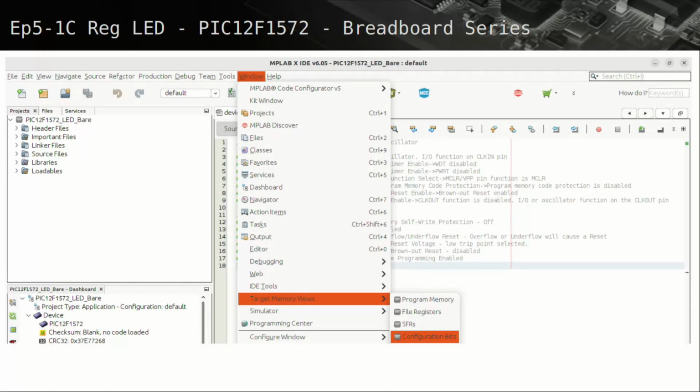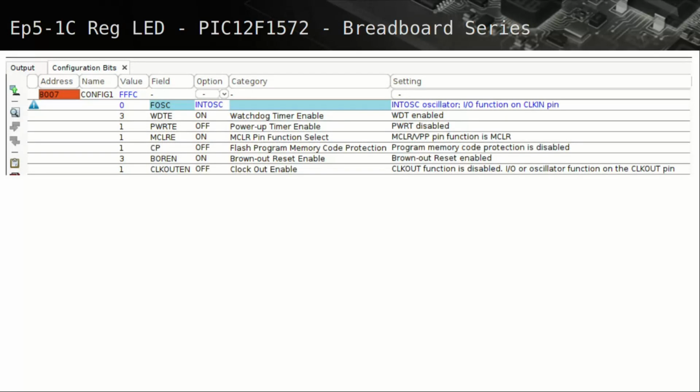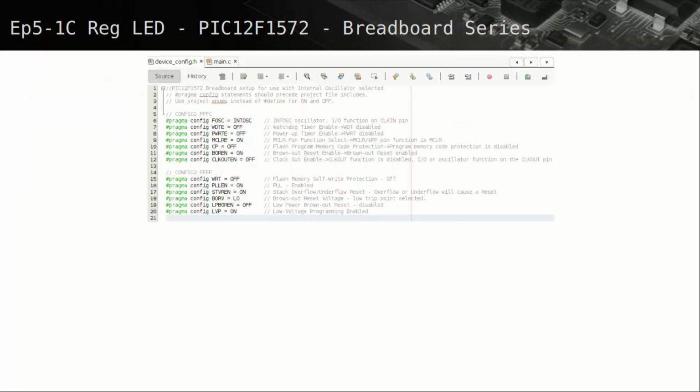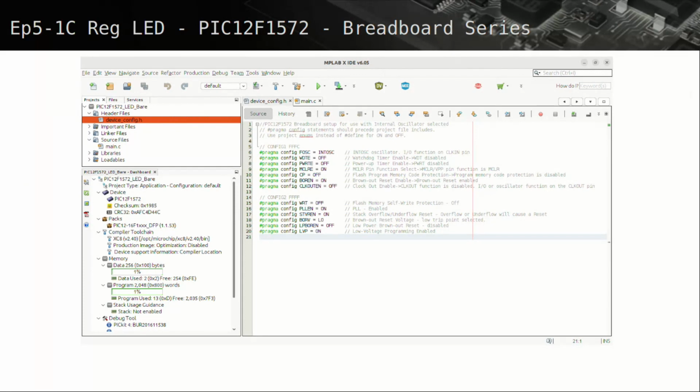The PIC device configuration bits are found from the same menu used for the assembly tutorial, and when using the C compiler, use a slightly different pragma format. Similar principle though. Only the FOSC field option is modified to INTOSC once again. Generate source code, copy the output text and paste into a new header file we create using a similar method as creating the assembly ASM file, but this time using the header file folder to create the new header file.